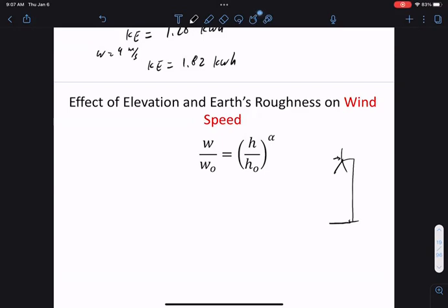So this comes out if we measure at H0, I want to compute the speed at H. I have elevation H0, which is convenient for you to measure. Then you want to change to a different height and compute the speed without remeasuring. Measuring wind speed at high elevation is not trivial. This relationship is basically given by this sort of scaling factor.